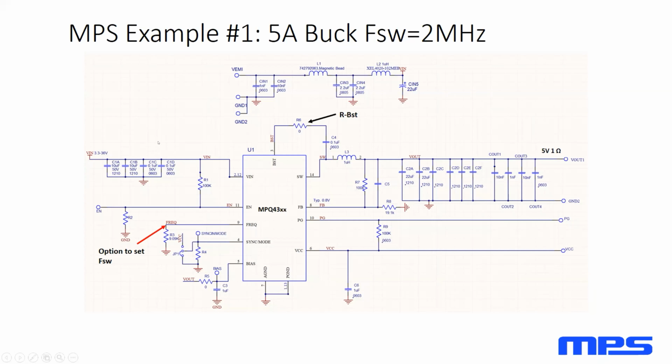So making sure you have the right case size, voltage rating, and nominal capacitance selected is very important. Generally the vendors for the capacitors will have that information listed directly on their website or available to you, and you definitely need to check the DC bias characteristics of the capacitor you're selecting.